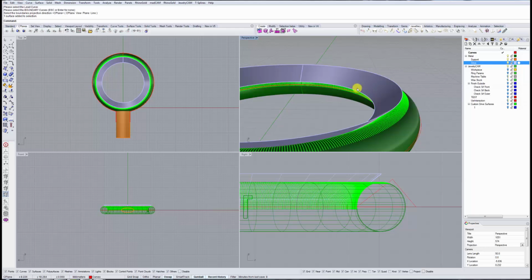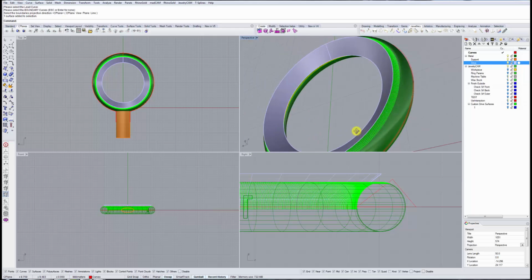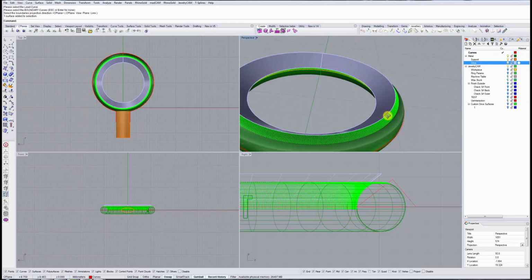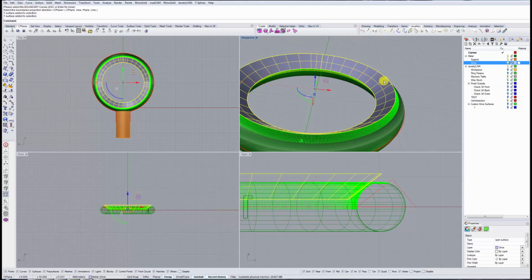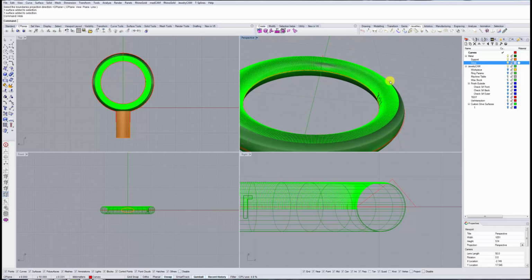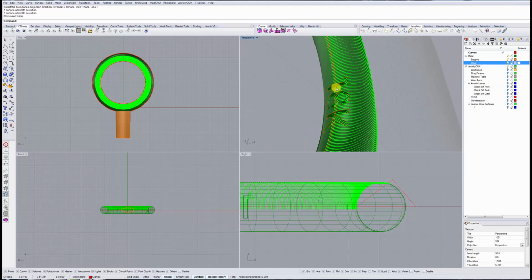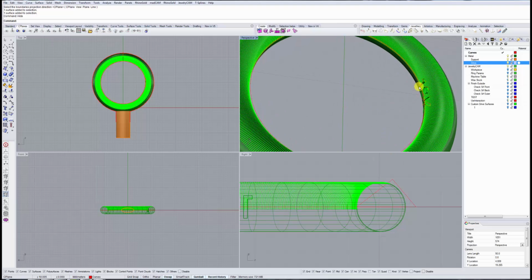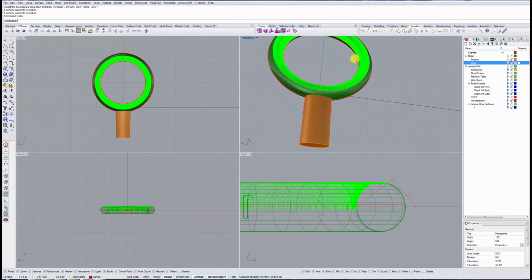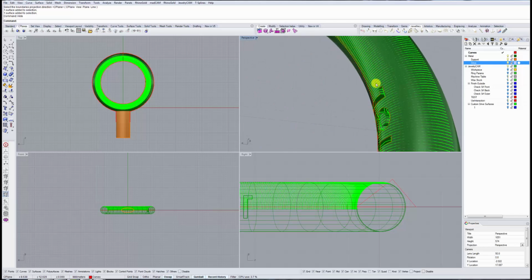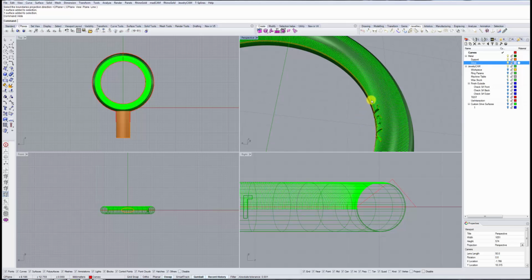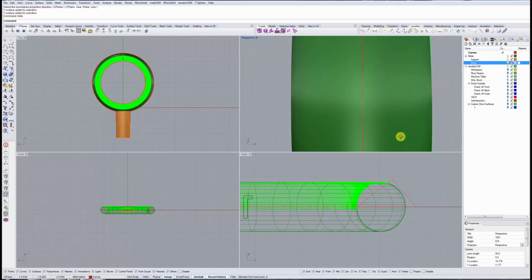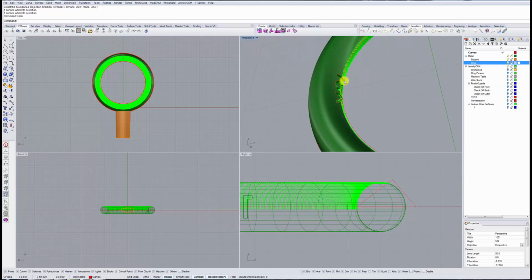It does not really need to tilt the other axis any further, so this will give you a good cut. And incidentally, you will notice that this will allow you to cut your engraving on the inside quite nicely. Of course, you don't always want to go around the full ring just to cut one segment, so you can do a partial sweep just to cover this area, and you might have to go to the other side and cover it here.